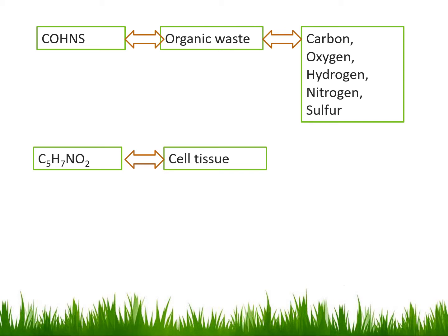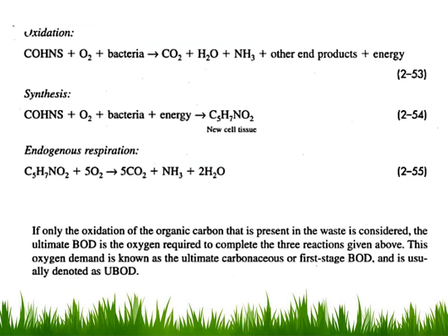If you have a view here, you can see how we will be converting the organic content into the simplified form, and then you can observe how cell tissue is being formed, and this is a better version of the same equation: oxidation, synthesis, endogenous respiration process. So these three equations are going to demonstrate the whole process of the wastewater degradation process.